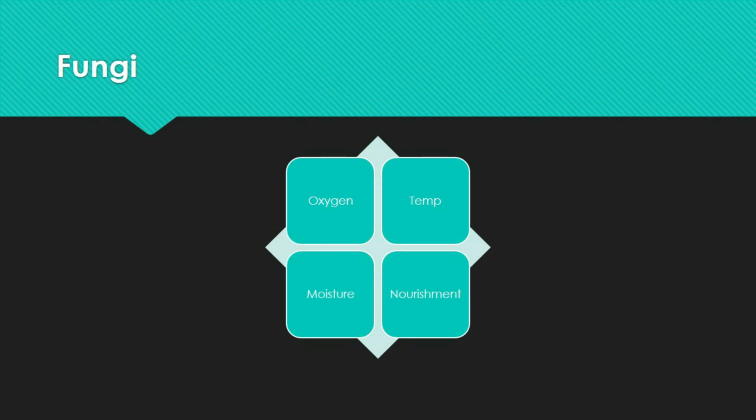Temperatures for optimal development vary from 17 to 35 degrees Celsius, according to tests that have been conducted in various labs and utility companies. At freezing or slightly above freezing temperatures, all fungi show little or no development. However, temperatures considerably below the freezing threshold do not kill most wood-rotting fungus, and they can survive the cold of winter in a dormant form, and if other requirements are met, resume active development again when the temperatures rise again.